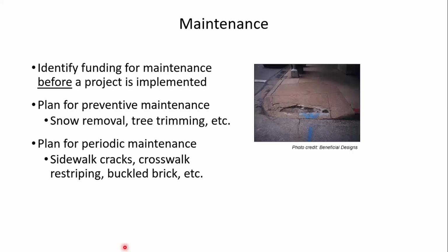Plan for periodic maintenance to deal with sidewalk cracking, crosswalk restriping, or brick or pavers that have become buckled or heaved up. You need to plan for that type of maintenance as well. And maybe that should be part of design, to try to come up with a design that reduces the need for maintenance, like maybe concrete slabs rather than brick or pavers. Even though the brick or pavers may be more aesthetically pleasing, there may be maintenance issues associated with those types of surfaces.